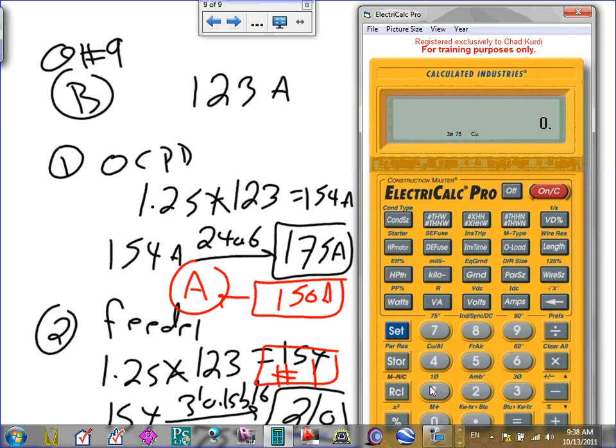Yes, sir. I want you to let me know if we are doing an overcurrent protection device on this kind of calculation. I want you to tell me when to use a table: 430.52. Table 240.6. No, table 430.52. Only if you have a motor. Have I told you that this amp is a motor? You know, guys, when you size things, if it doesn't say motor load, then you don't use 2.5. Only for motors.